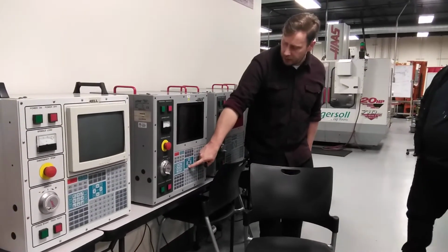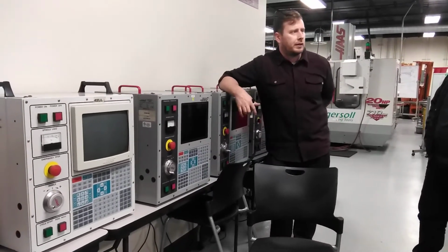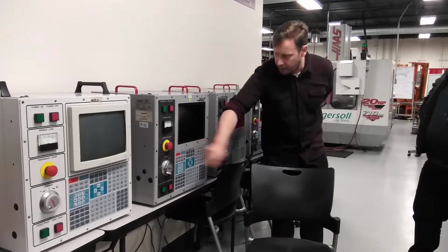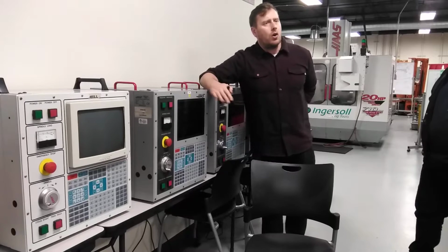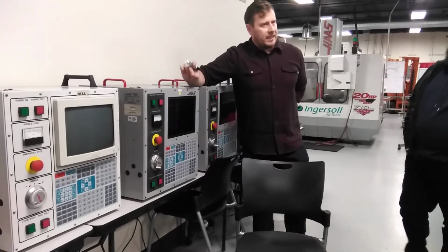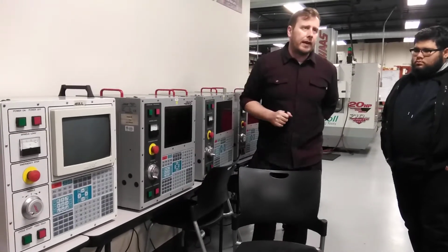So you're going to come down to tool 4, and what number are you going to put? 250. Now the machine knows where to find that value. So you'll put D04 in your program, and the machine will call up that number.